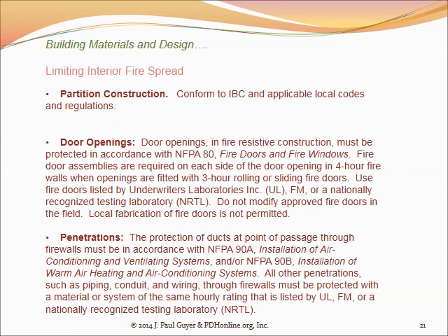And in the more advanced systems that are mandated for larger and more sophisticated buildings, is that through a strategy of duct modifications and automatic dampers and fan controls, in the event of a fire, the primary fan that is moving the air conditioning air around the building is maybe shut off, or a second fan will come on, and with the duct configuration and the automatic dampers and the fan controls, the air conditioning system switches to an exhaust mode and exhausts automatically the air and the smoke from the location in the building where the fire broke out.